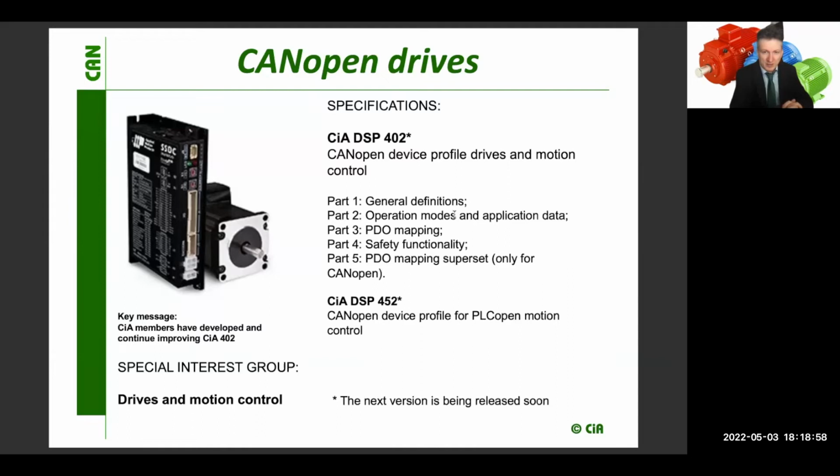Part 4 is CANopen safety and EtherCAT safety. They are not standardized. There's just a specification, which means that in case you would like to design them, you have to become our member to get access to the specification. And for CANopen safety, you have to discuss every step of your development with a functional safety authority such as, for example, the German TÜV.